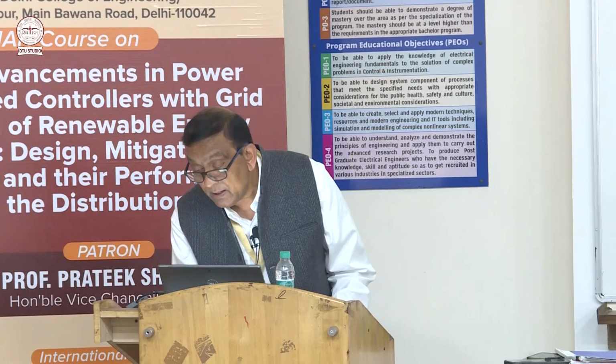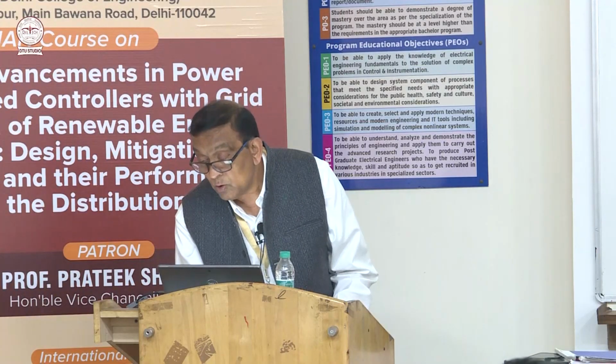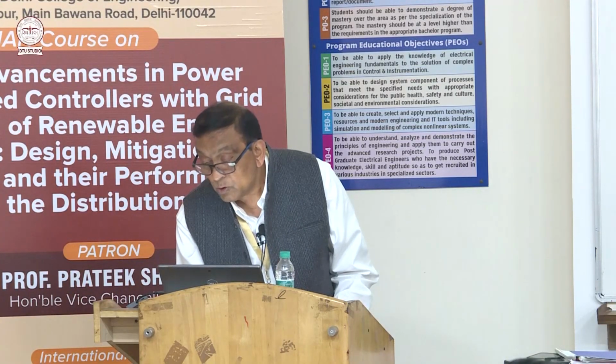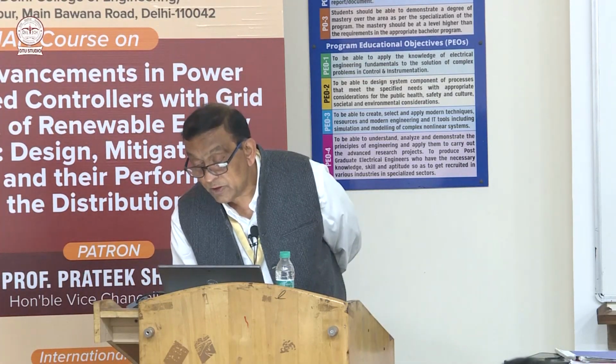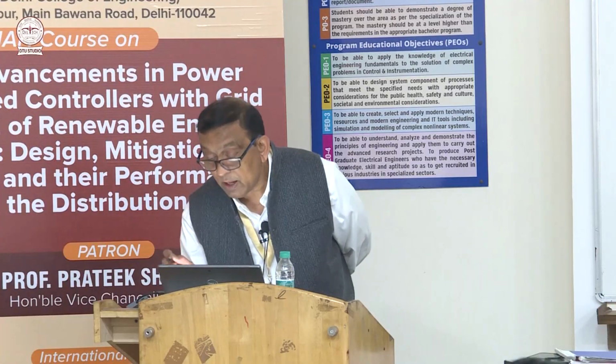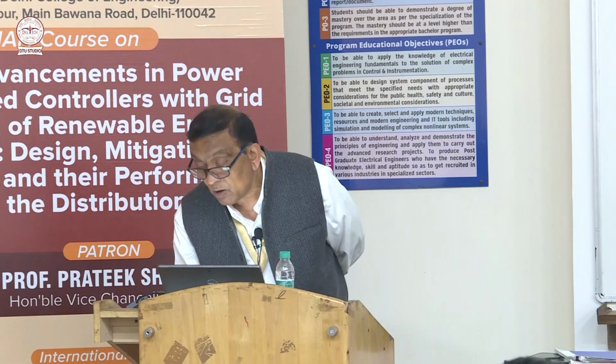The drop in the resistance and the drop in the reactance of the source current gives the source voltage. So without the shunt active power filter there is no voltage regulation, and the load voltage is much lesser than the source voltage.